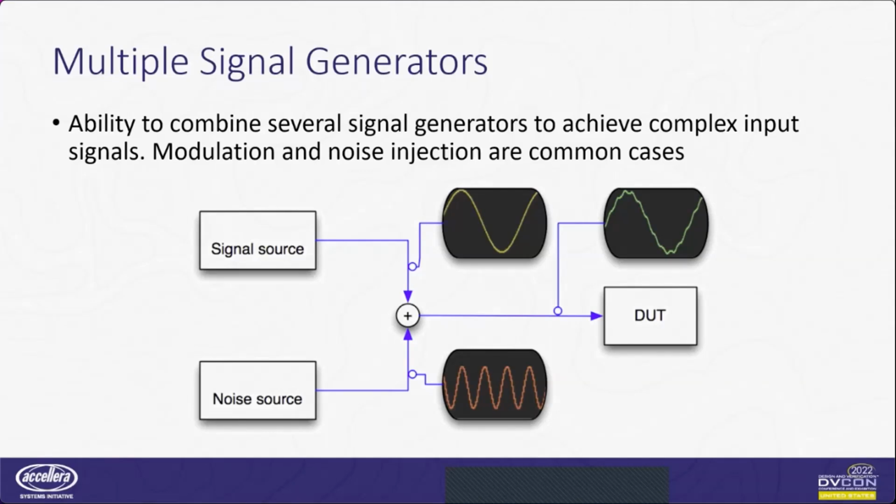So I don't care whether it's actually a SPICE model or a real number model in a DMS verification or whatever, right? The idea of abstracting that information allows us to create the test at a high enough level to say, okay, I want to generate a sine wave of this frequency starting now, and then do some other stuff. And when I get some other signal back in, maybe if I get some particular transaction on the bus, I say, oh, okay, now I want to double the frequency of the analog signal or whatever, right? So I can recognize that and then send another transaction to tell the signal generator to change.